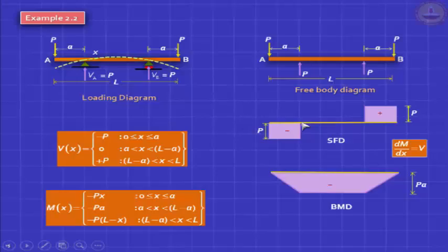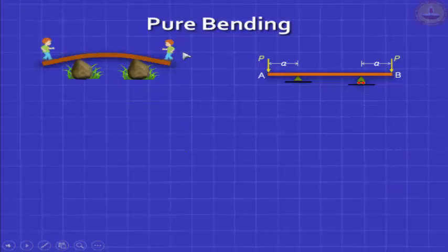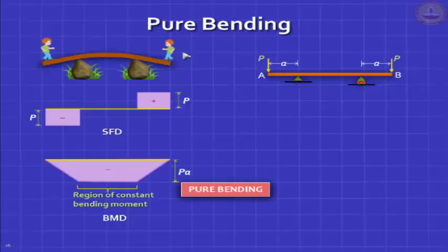Look what's happening here. Only where you have pure bending, you will have a segment of a circle. This is impure bending. The impurity is the shear. So please note, in this region it's a segment of a circle. Here it's not. The radius of curvature is going to vary. So good answer. So let's look at this. The pure bending is going to be only in the middle region. And you can see that this tangent here is not matching here, but in this region it's matching.